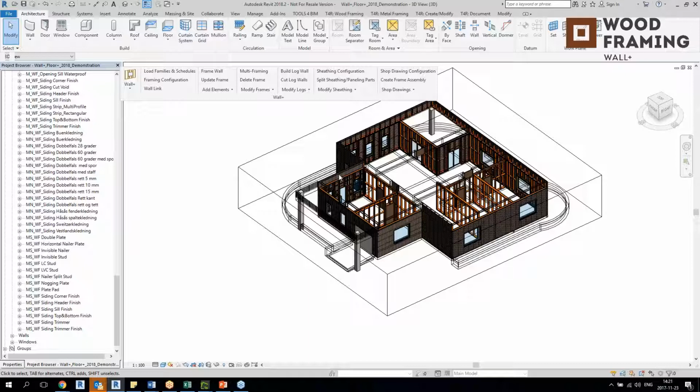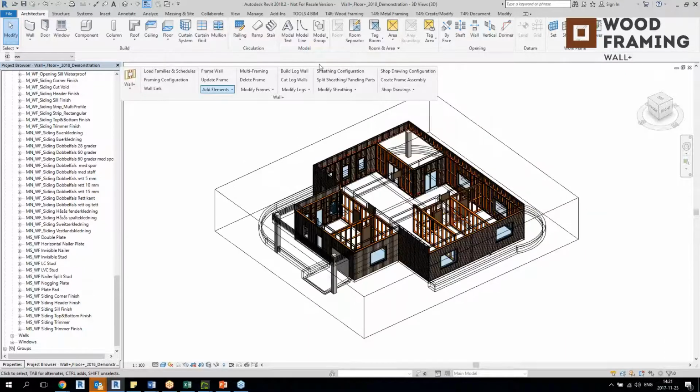And after you set up your template project location and are sure that you have all the necessary families and templates in the current project, you can go ahead and create frame assemblies. And your assemblies will have views and schedules placed on sheets, just like in the template project for the selected configuration. So as I mentioned, we don't have any assemblies created right now.